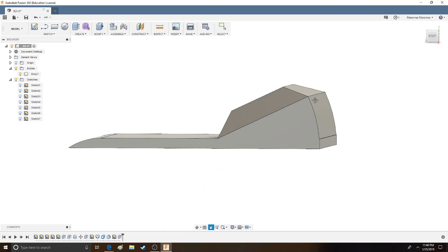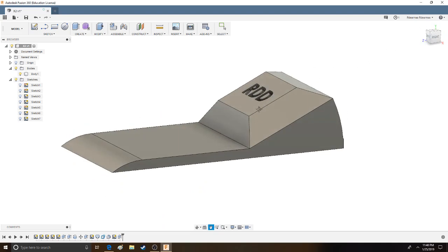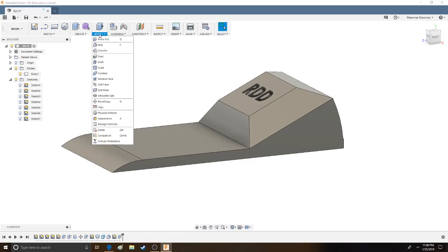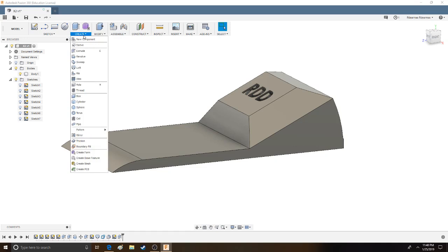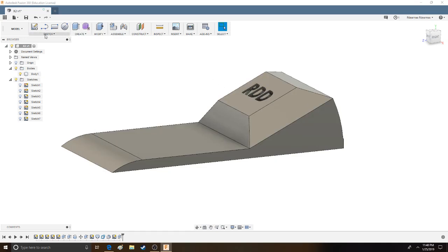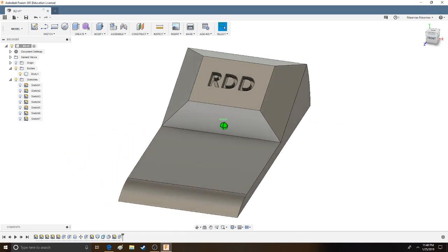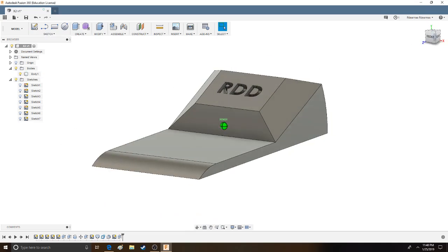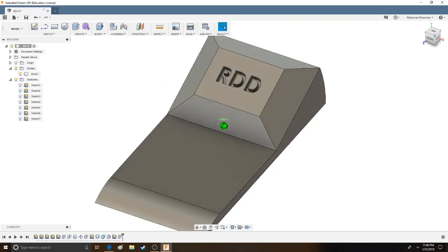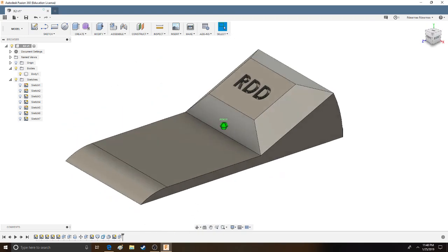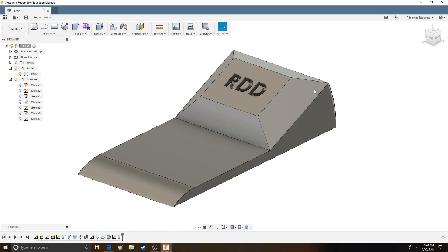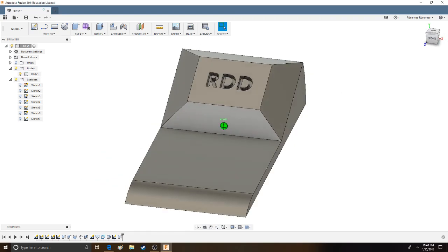So gone over, we use the revolve tool, the fillet tool, and, how could I forget, the loft tool, and by using the text option in Sketch and extruding it down, we made a really quick custom doorstop with little to no time. It's fairly quick how to make something like this.